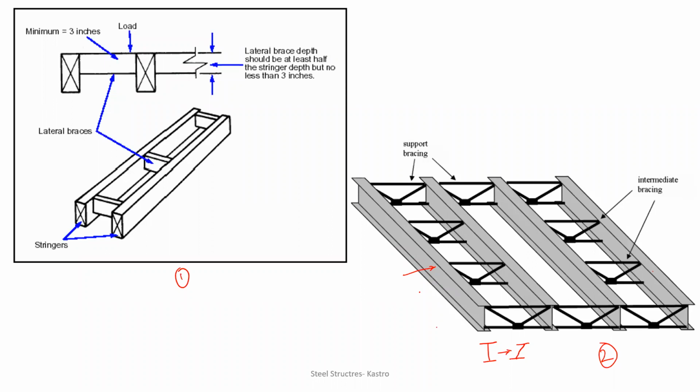Now, your motive is to ensure that the member which has got bent is in a stable position. That means it should be in the perfect I shape. Now, what will you do? The only thing which you can do is to provide supports, the thick colored things which you are seeing, in order to resist the bending of the member. And hence those are called laterally supported beams. So if you are providing support in between the two sections, then those are called laterally supported beams.